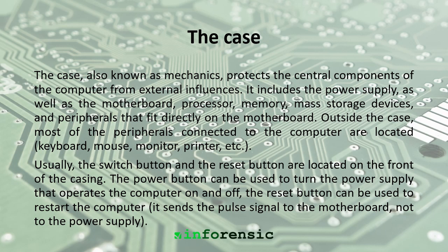Usually, the switch button and the reset button are located on the front of the casing. The power button can be used to turn the power supply that operates the computer on and off. The reset button can be used to restart the computer. It sends the pulse signal to the motherboard, not to the power supply.